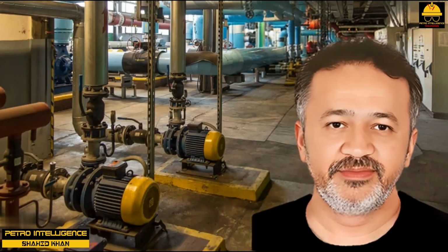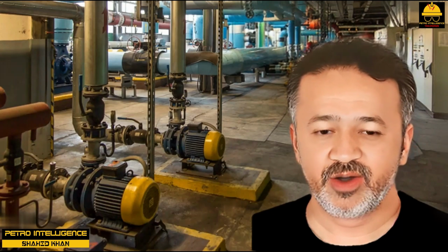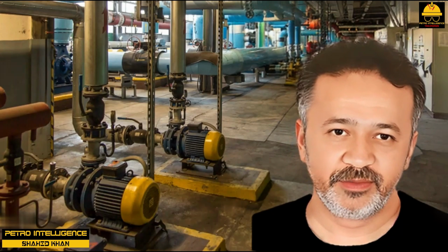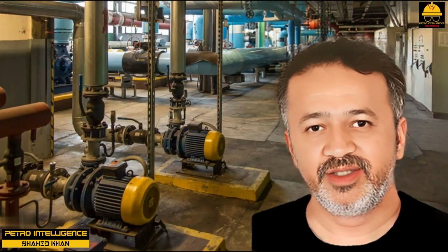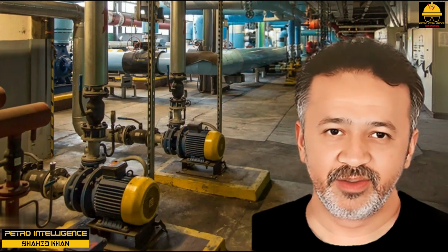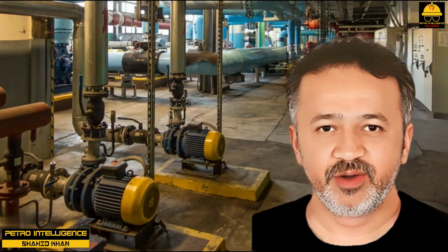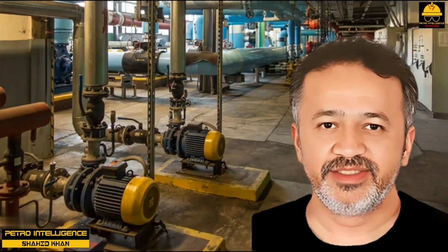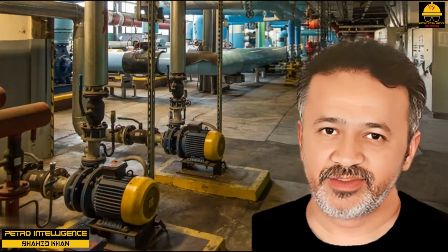Selecting motor size. We noted in the Centrifugal Pumps Fundamentals lecture that increasing the impeller diameter might require a larger motor for an existing pump. Suppose, then, when a new pump is purchased, we install a 100 horsepower motor sized for the maximum 10-inch impeller, which the pump could accommodate. Actually, only an 8.5-inch impeller would be used in the pump initially. This 8.5-inch impeller requires only a 60 horsepower motor.